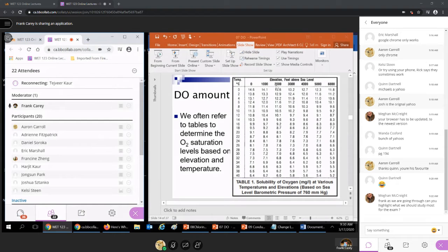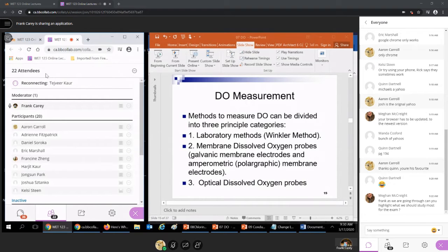I'm sure there are some tables out there like that. And so you just cross-reference elevation and degrees centigrade, and you may want to ideally calibrate this instrument on a day where atmospheric pressure is normal, and normal being about 760 millimeters of mercury. And that you can get from the internet or weather channels or whatever.